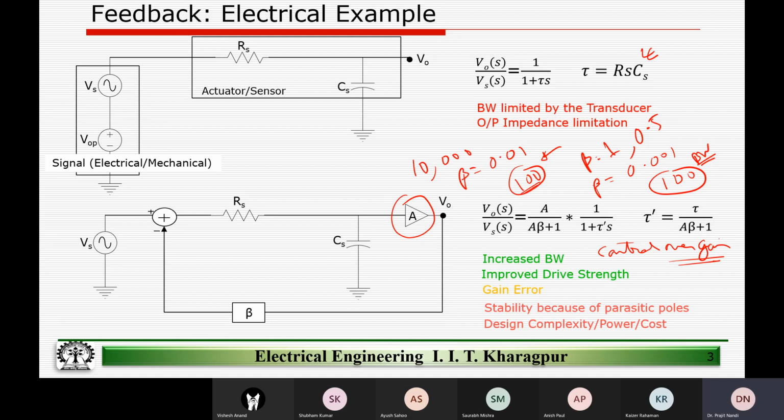So the point is, we cannot unilaterally set the beta value and become greedy and say, okay, I have achieved a high gain, because all the parasitic poles that are going to come here are going to create problems if we try to make the closed loop gain significantly large. We can make it, but then the design becomes extremely challenging, right?